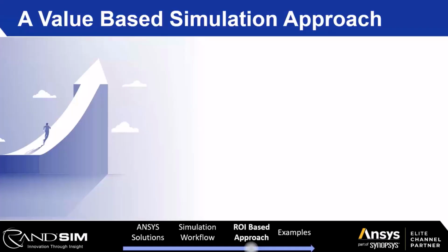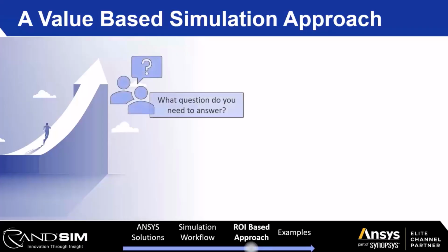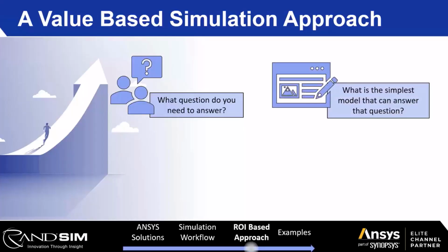And so to do this approach, I like to ask myself two questions anytime we start to dive into doing any sort of analysis. The first is, what question do you need to answer with a model? Right? This is getting at, what is the purpose of us running an analysis? What are we trying to understand, right? So for a power distribution unit, it might be, I want to understand what temperature a bus bar is going to get if it's passively cooled as opposed to force cooled. And then the second is, what is the simplest model that can answer that question?